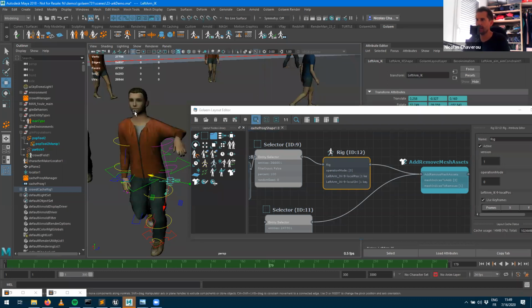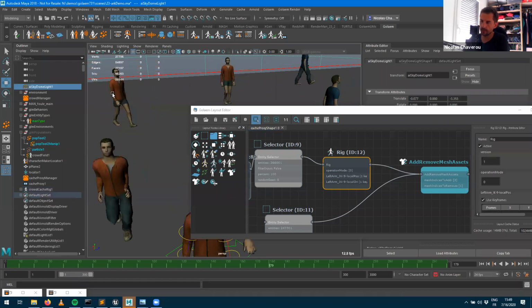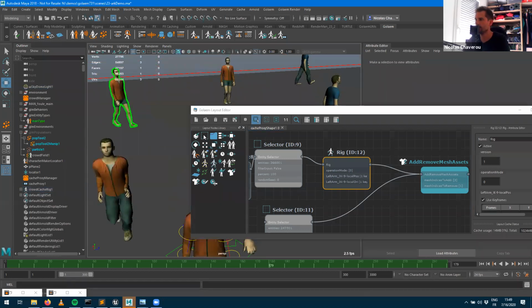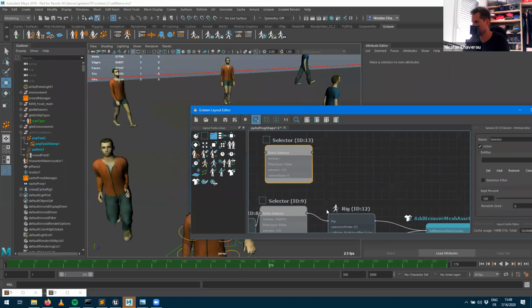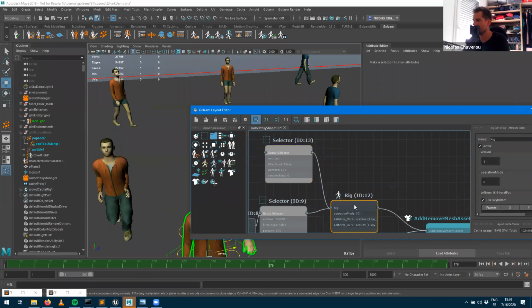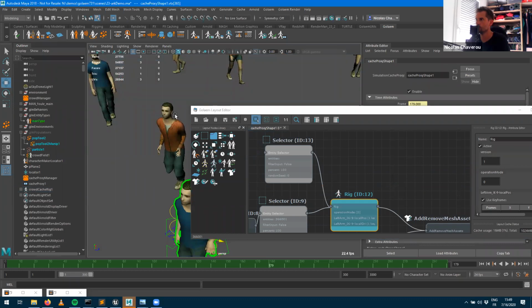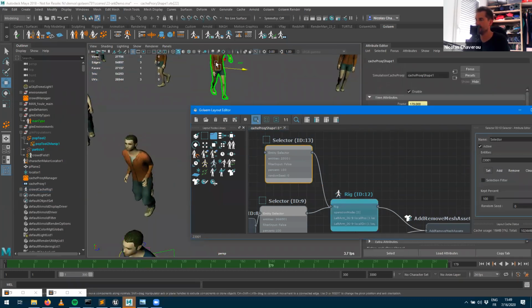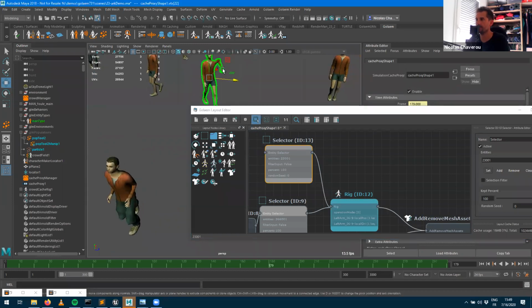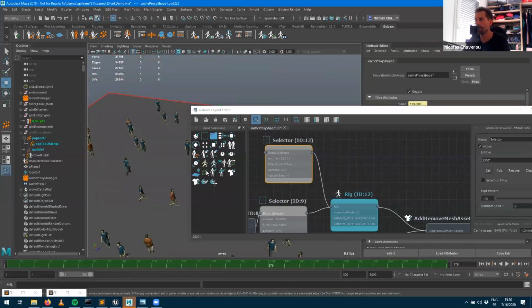And once again, you want to apply the same deformations onto maybe that guy here. I'm going to press F9, select that guy, bring a new selector. Oops, it's starting to get messy. I should have grouped this. And apply that deformation. And what's happening? Oh, sorry, the selector was empty. So set. Yeah, and now that guy gets applied with the same keyframe system that you've been specifying onto the other character.